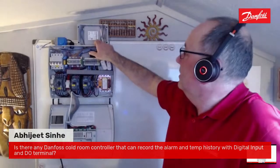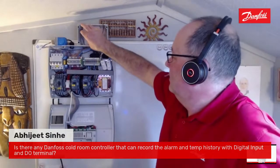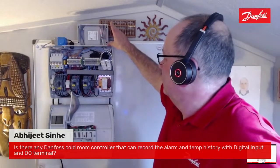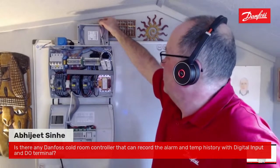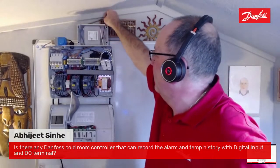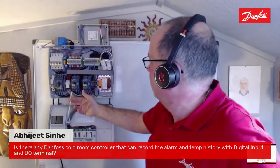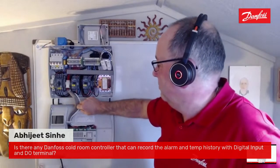On the top of this controller up there, we've got a Prosa PRSC4, which is a little temperature monitoring device that I've rigged up on this site. Basically this has a GPS signal, so you can see the antenna there. It's linked into the Modbus on the controller via the cable here, and this will send alarms straight to your mobile phone.